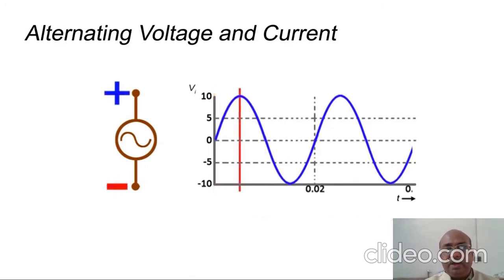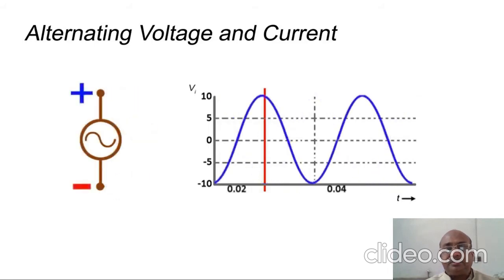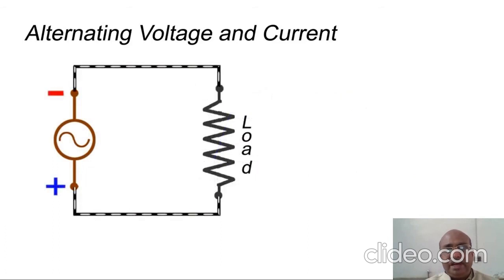This way, you can see here, during the positive half cycle, it attains the maximum value, and when the cycle changes, it takes the value of 0. Now, you can see in this graph, in the negative half cycle, the maximum amplitude is in the negative direction. This is the way AC current pulsates.